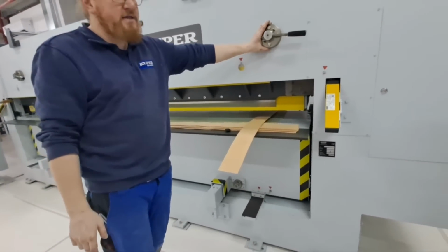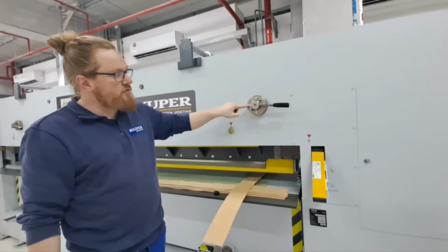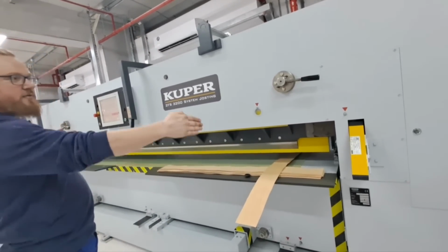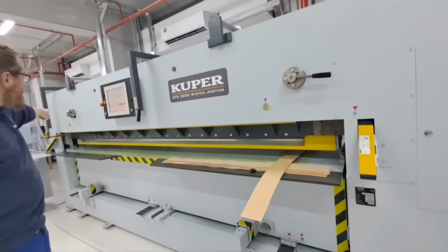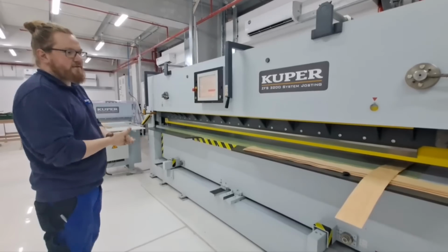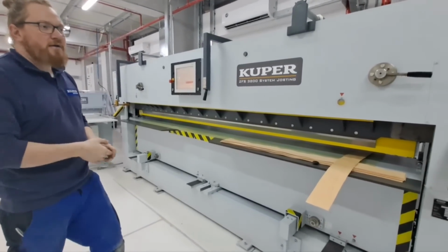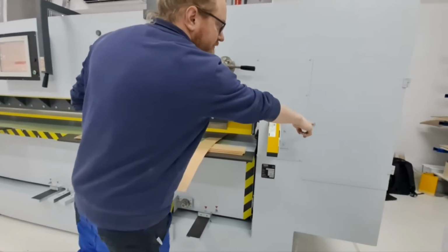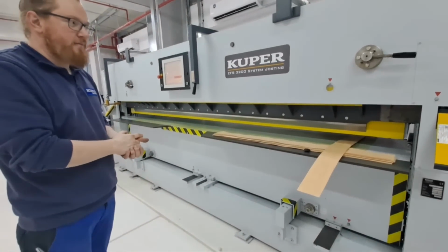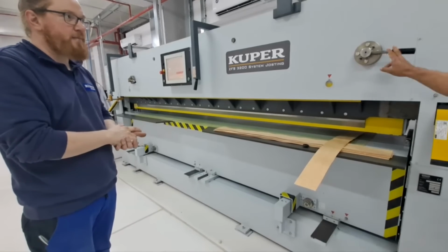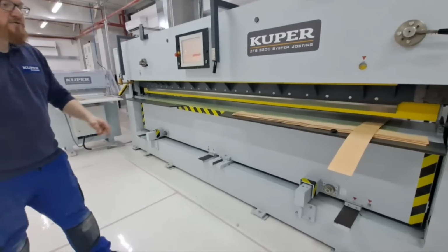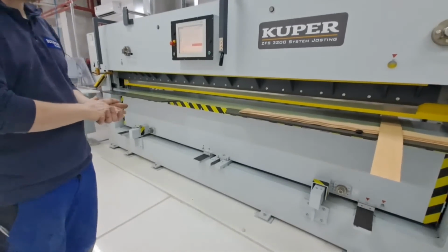The same for the top plate here, where you have to loosen the four screws here and move the handle a little bit, so we can adjust the blade on the right side higher or lower, and the same on the other side. So that's to adjust that everything is parallel, and with the nut over here, you can adjust the bite of it. So this one and that one is for the top blade. These two are for the blades behind. Goes for the lower knife.